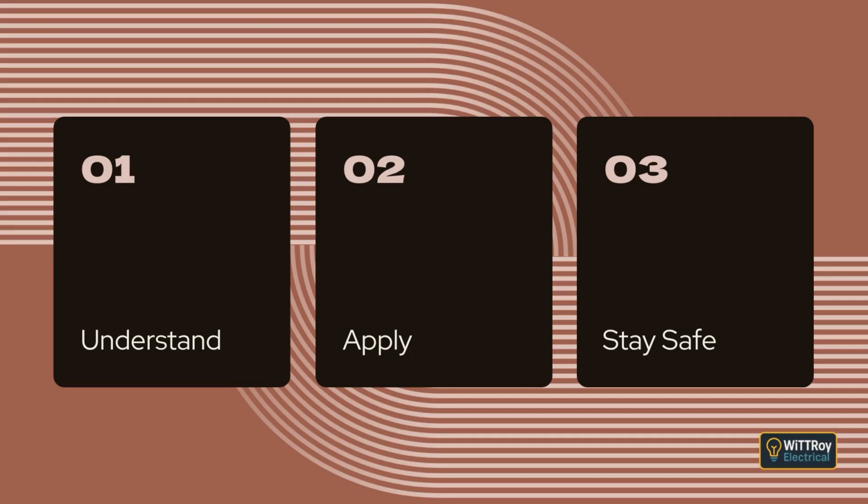Clause 3.11.4.5 Identification of underground wiring. Underground wiring must be identified with orange marker tape. The tape must meet the requirements of the relevant standard and should be positioned roughly halfway between the wiring system and the ground surface, or halfway between the wiring system and the top of the mechanical protection.